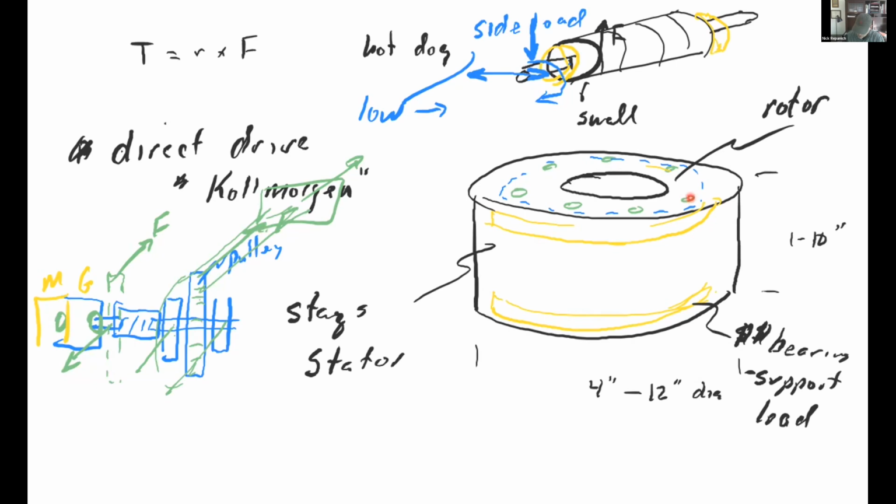Over here, the load attaches directly to the motor, and there are 0 springs in between the motor and the load, 0. So when the load moves, it moves exactly the same as your motor. Your transfer function gets rid of all of these K terms.